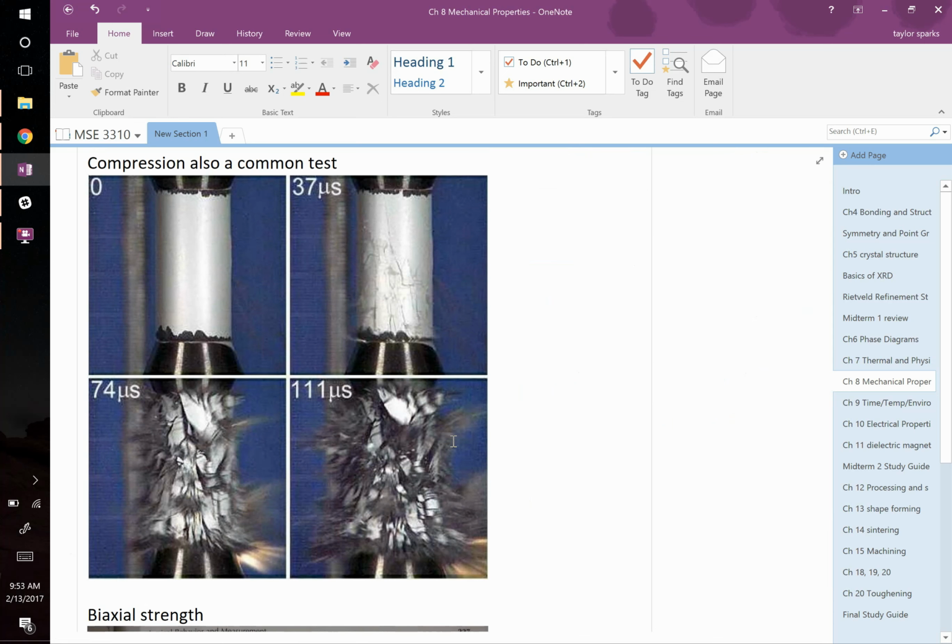Like this is microseconds, right? But take a look at this. Some of these are vertical, but you'll notice that a lot of them are actually at 45-degree angles, right? So that, and maybe in the mechanical materials class you're talking about this, what's happening is that it actually fails under shear. That 45 degrees is where you maximize shear, and it is much weaker under shear than under just smashing bonds together. That'll make them slide past each other in shear.